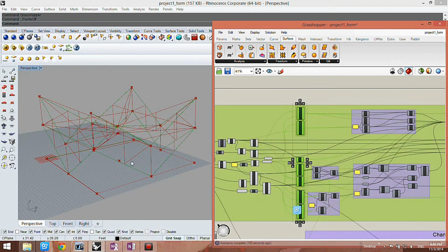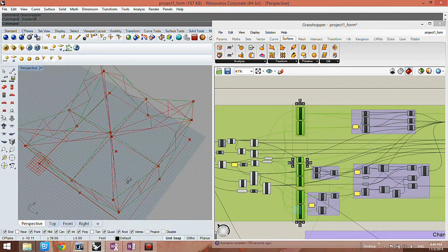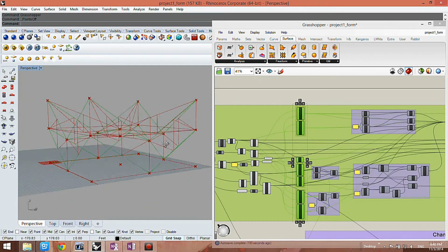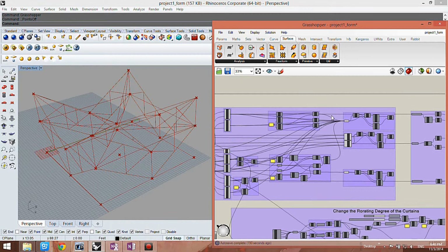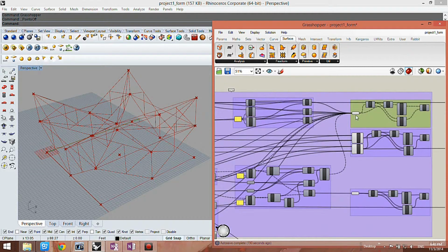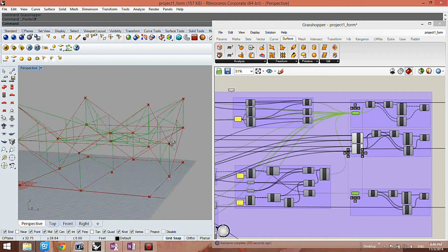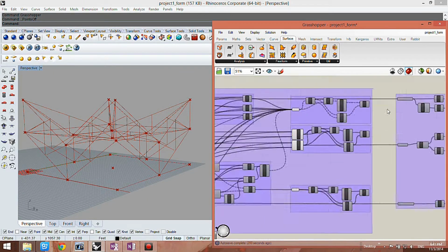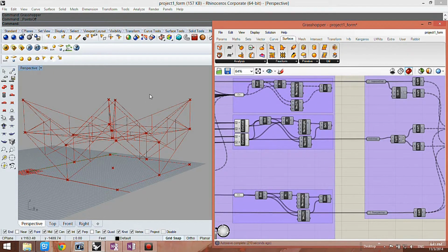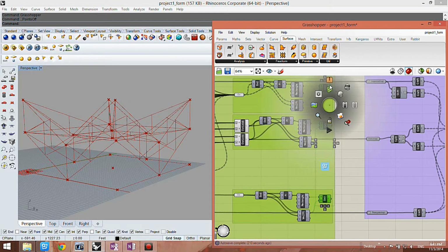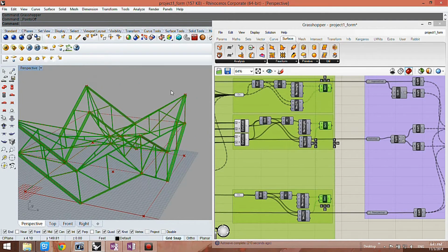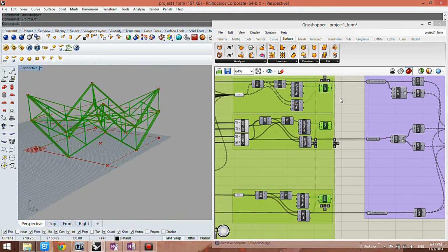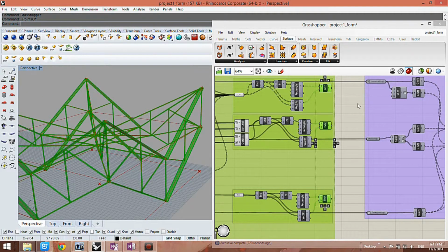And from here, I just got which I call the primary frames. That's the main structure that supports the pavilion. And from these lines, I get these secondary frames here, which work between the primary frames. And then I gave a volume to all these frames that makes them look more realistic. I just set a section for each of these baselines, and then by extruding, I get all the frames.